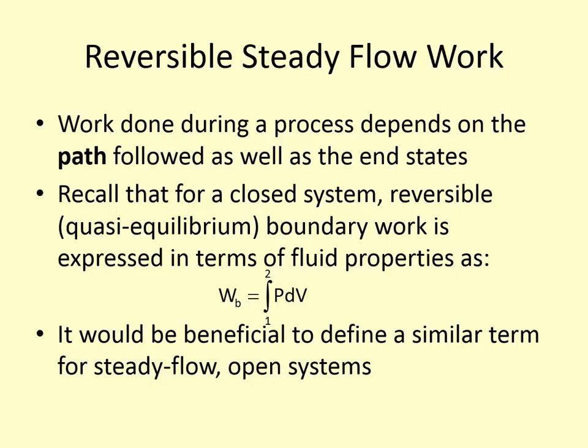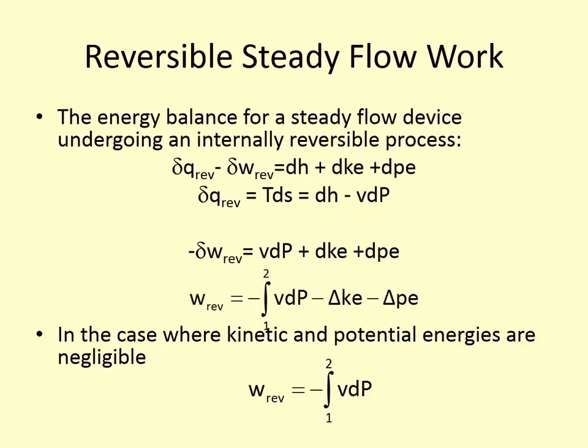So using what we know about the systems and their relationship to entropy, we now can develop this equation for flow work. So we needed some additional background and information before we could develop it, because it relies on the Gibbs equation, which relates entropy, enthalpy, specific volume, and pressure, and internal energy one to another.